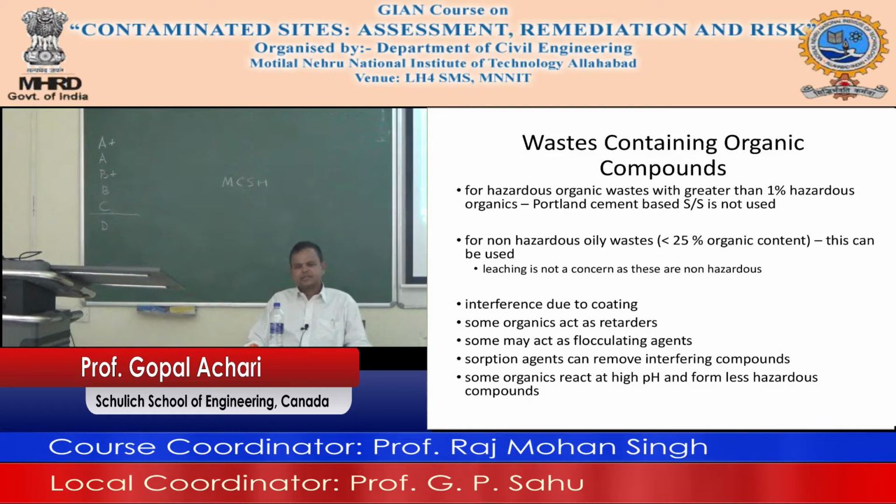How do you retard it? No, not gypsum. Gypsum is okay, but how do you retard a reaction? What about sugar? Did you try sugar? Yeah, you use sugar, right? Sugar is an organic, it's a retarder.